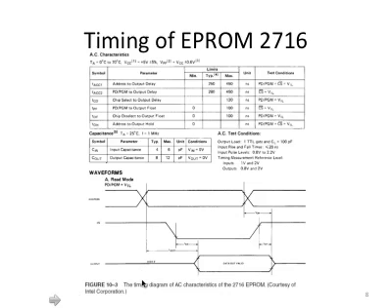For multiple line signals like this output or this address, if you see a single line, that means during this time period, this set of signals are invalid. And if you see a shape like this, as a box, that means this is when that set of signals are valid. Okay? So what we see from here, this timing diagram example, if you start counting from the moment this chip